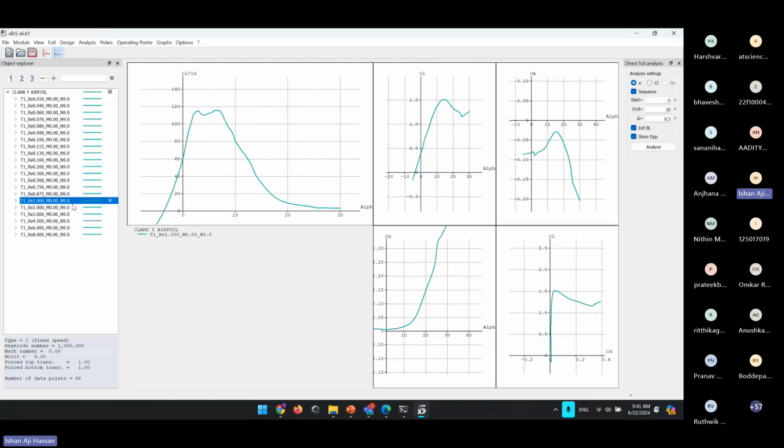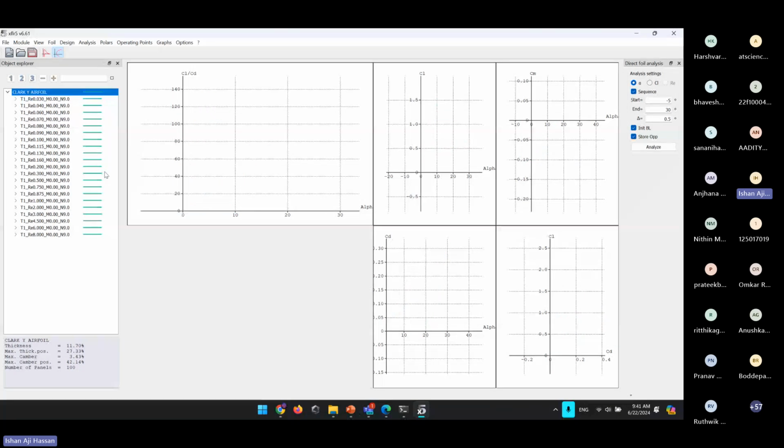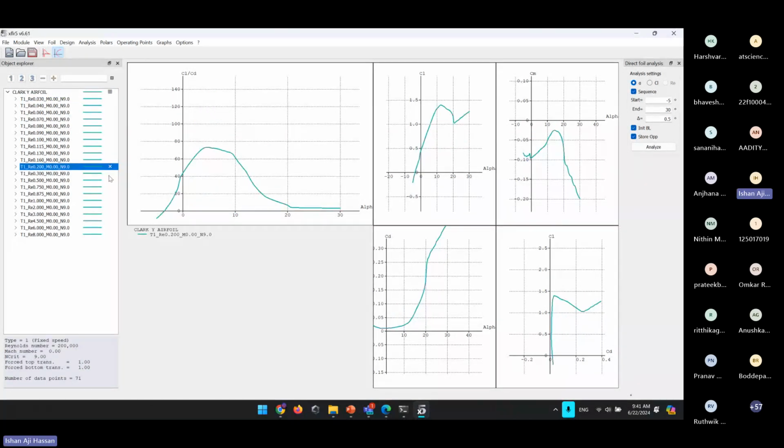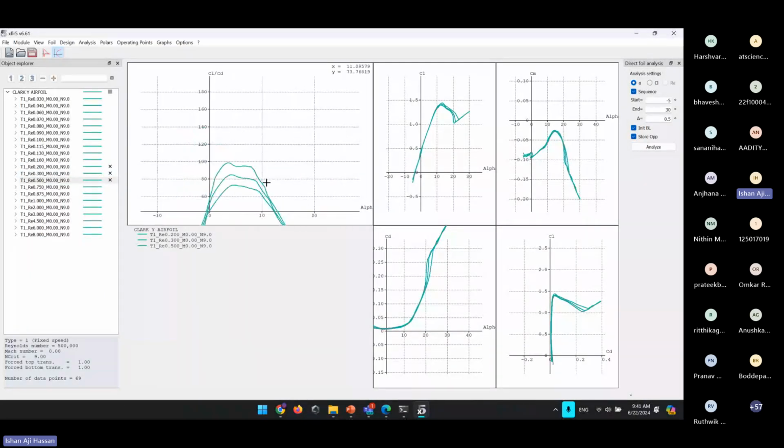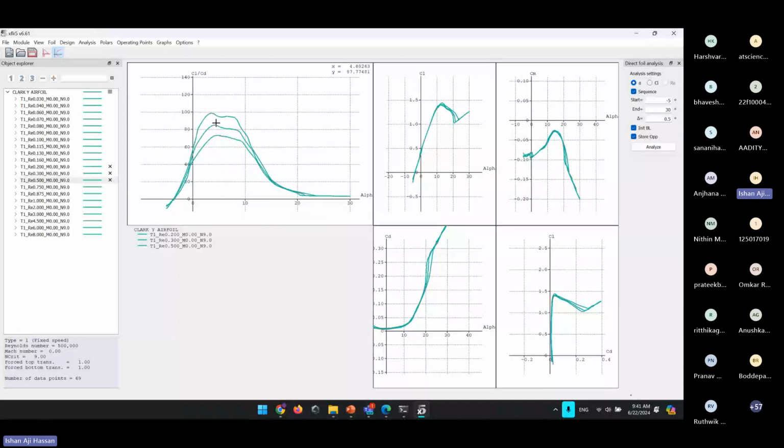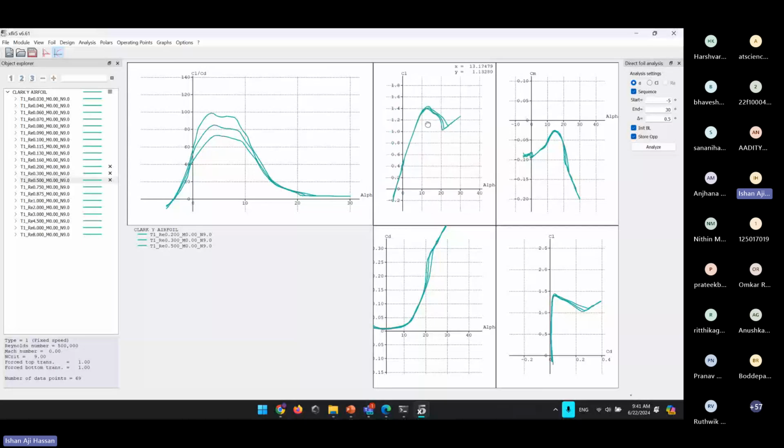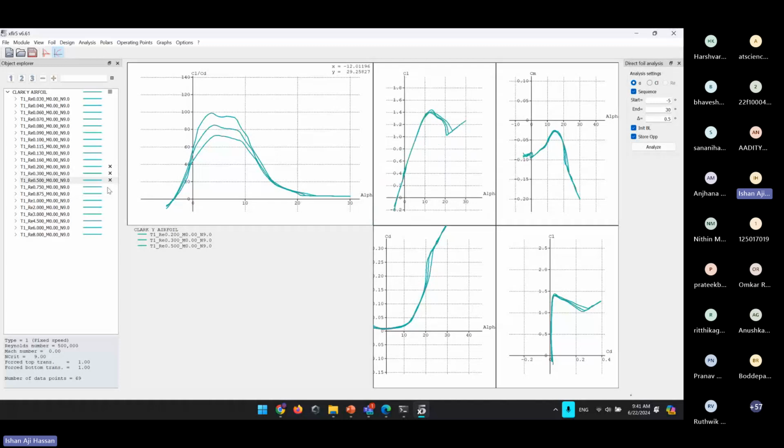So yeah, what we can see is if you're considering relatively higher Reynolds numbers, I'll start from 200,000. As you go to higher and higher Reynolds numbers, the efficiency curve shifts higher. That is, CL by CD becomes higher and the flight becomes more efficient. Another thing you can see is the CL graph is almost exactly the same. But as you add more Reynolds numbers, you can see a bit of a trend.